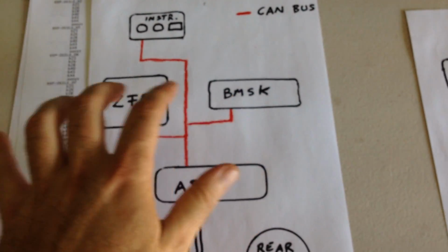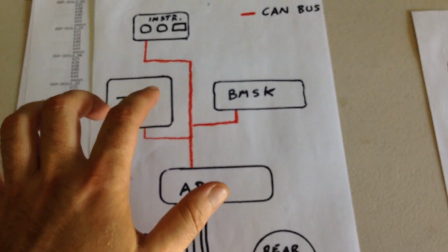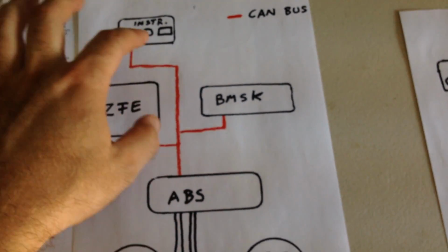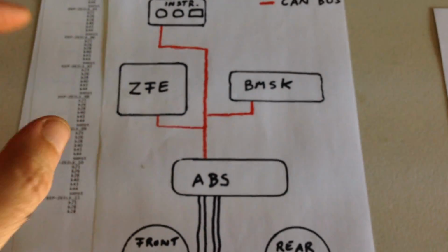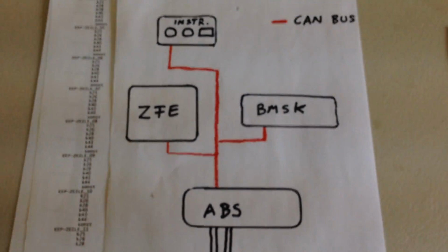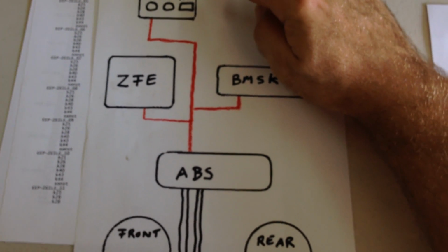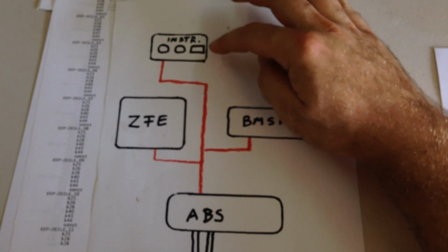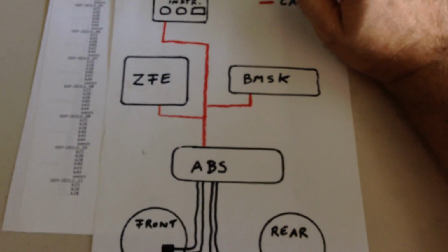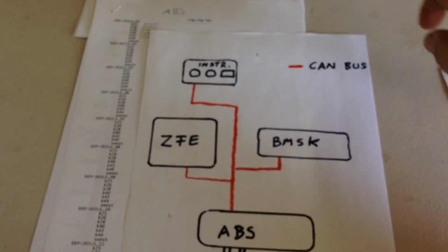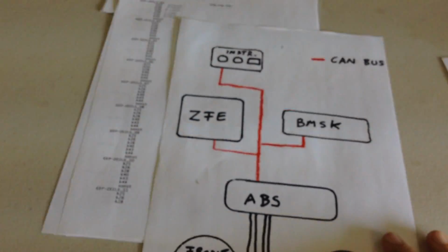It has no interest in this data package. When the data package is floating around in the CAN bus system, the identifier of the correct address is your instrument cluster. So then the information is turned into a signal, and turns the gauges.